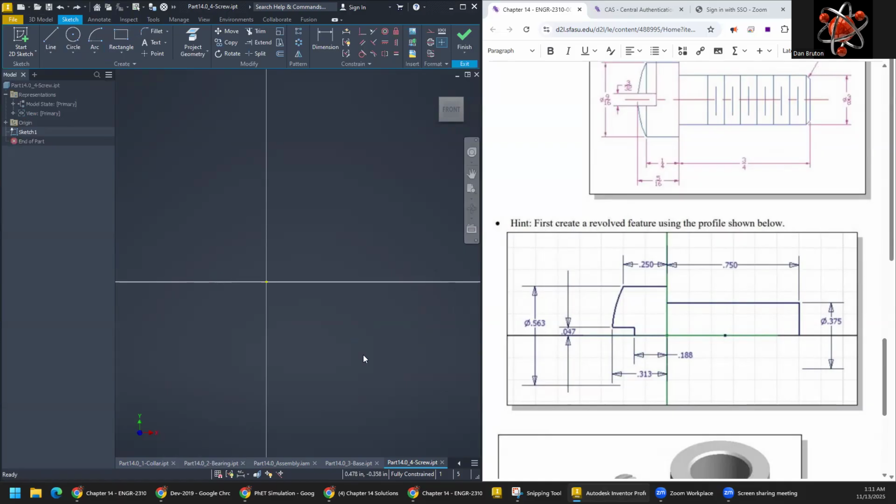So why did it decide to do that? Maybe it's the directions that I had it placed or drawn or pulled. 0.75 and oh yeah, you know what? What we can do is use our special line called the center line and go all the way out there. Click on that line. Let's make sure it says center line. It gives it that dotted line appearance because that's going to allow us to go between those two.